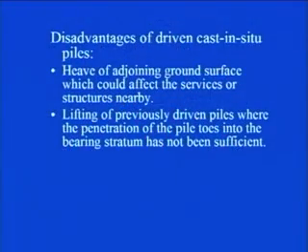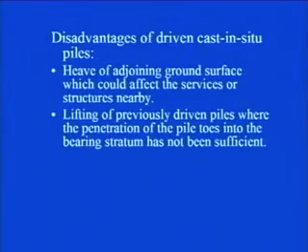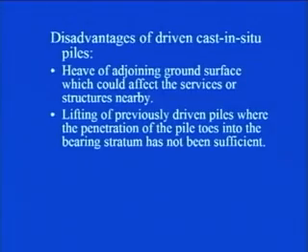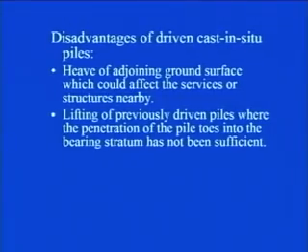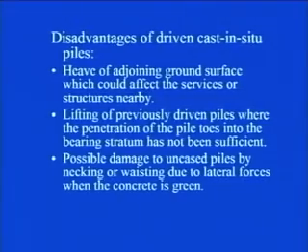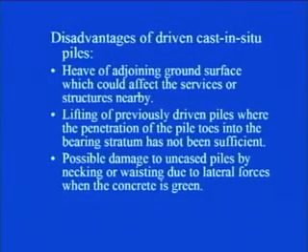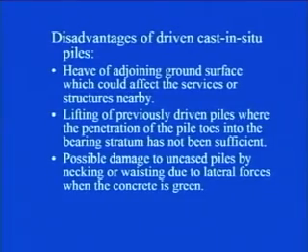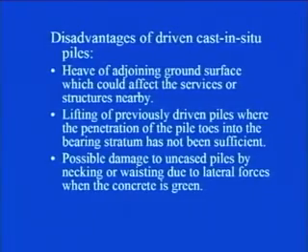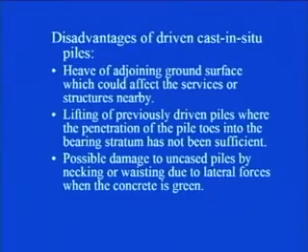Lifting of previously driven piles where the penetration of the pile toes into the bearing stratum has not been sufficient. So, that is again one of the disadvantages. Possible damage to uncased piles by necking or wasting due to lateral forces when the concrete is green. Let us say the concreting is going on and the concrete is green.